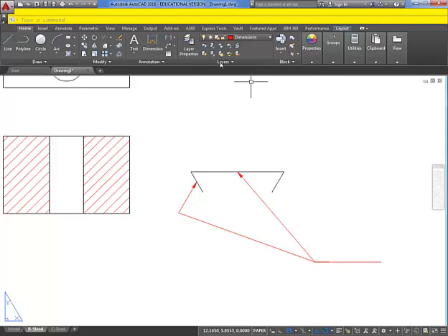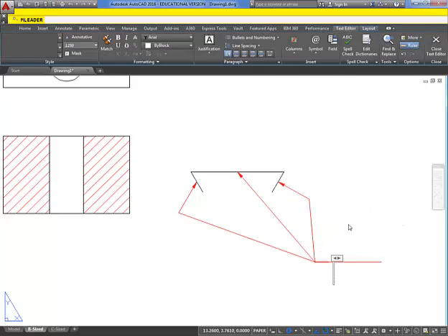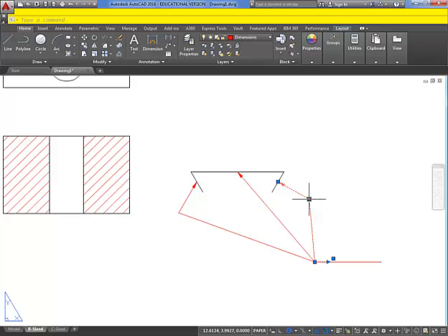So even if I maybe wanted to have this point a little better at this one, I can maybe do something along those lines. That's awfully vertical though, don't like that, so I might adjust that a little bit. So feel free to go in and turn that off on the dimension style so you can get some nicer leaders that aren't pointing oddly at the shapes. And if you need help getting that changed, just holler at me and I'll help you do that. In fact, we could change that in a template so that you don't have to worry about that in the future. Does that make sense?